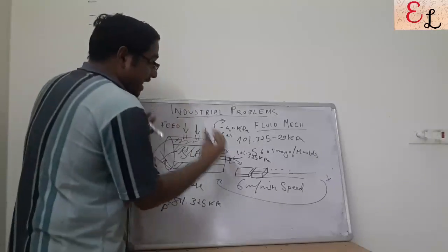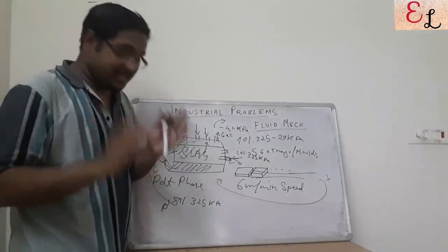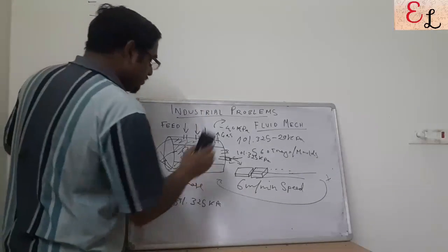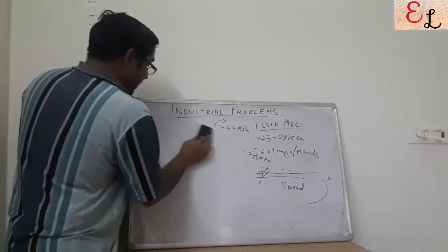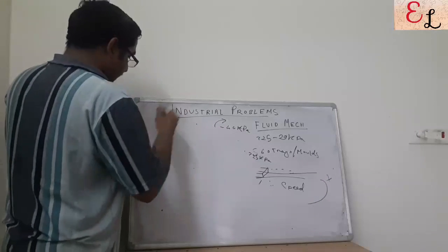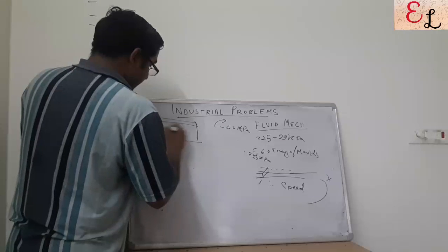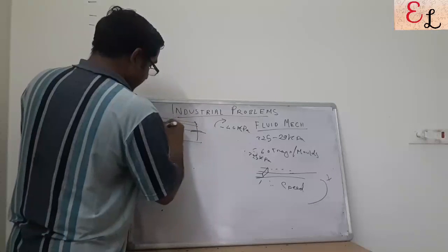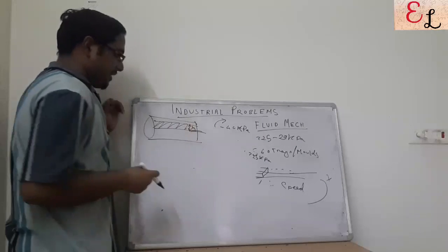When the slag stops coming out by itself, we will have to strike a pressure balance. I'm rubbing this out for a moment, and if I draw this structure like this, this is my bed above the tapping hole, with the height of h above the tapping hole.